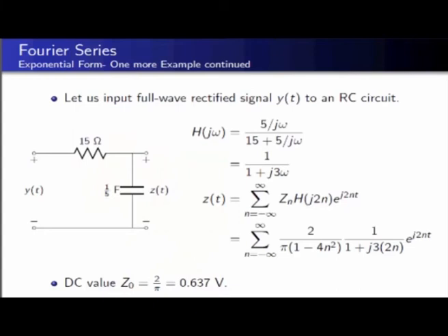So I've done all this now for periodic signal. I assumed input is periodic, and if it is periodic I can express it as Fourier series, and if I express it as Fourier series, then I can exploit the eigen function property of LTI to find out the output.